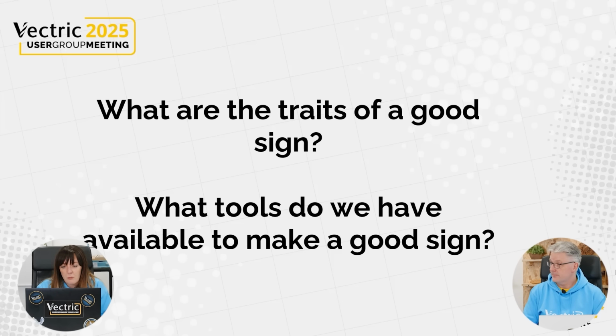So in VCarve Pro and VCarve Desktop, we add the ability to create texture toolpaths, which is a nice way to add a little bit of, well, obviously texture because that's what it's called, but add a little bit of interest to the backgrounds of your signs, or maybe even the foregrounds if you'd like to. You can do 2.5D stuff. So that's like using the geometry of your tool to actually create things like V-carving, prismatic letters, inlays, and so on, which really can up the interest in your sign, I guess I could say.